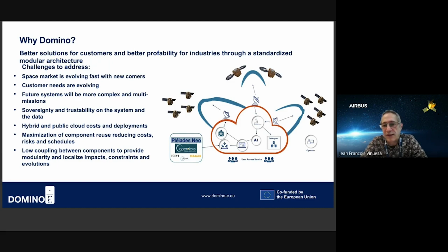When we talk about full system, we talk about, for sure, the instrument and the satellite that are going to be the flying system, but also the ground that allows you, as Michael showed, to control the mission, to order images, and then after to receive the image and also to make some products for the downstream sector, like verticals. Let's say you can have an image and you can extract information for agriculture, for change monitoring, for urban purposes, and also for defense. So when we talk about an end-to-end system, we talk about the flying system, so the satellite and the platform, and the ground segment.